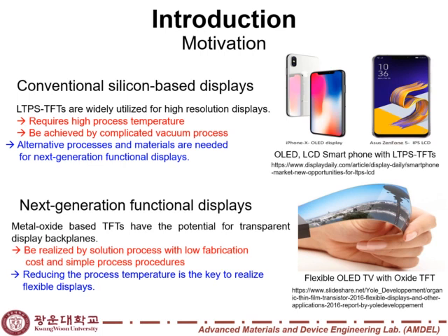For this, metal oxide-based TFTs, which are realized by a solution process with low fabrication cost and simple process procedures, can be used for flexible displays. But actually, this simple process requires high temperature of about 500 Celsius degrees. So reducing process temperature is the key to realize flexible display.